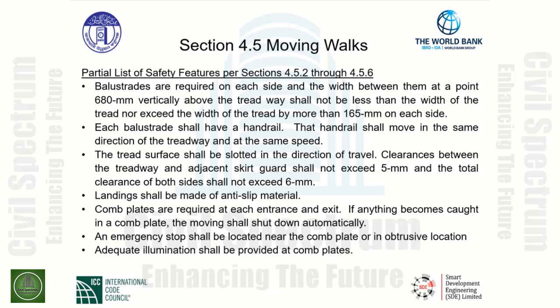The comb plates are required at each entrance and exit. If anything becomes caught in the comb plate, the moving walk shall shut down automatically. An emergency stop shall be located near the comb plate or in some unobtrusive location. Finally, adequate illumination shall be provided at the comb plates.